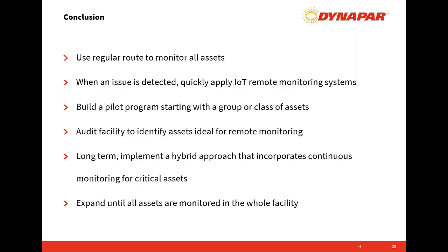And before every read, we have an internal calibration procedure where we check some internal parameters before the data is taken. And the unit is actually self-adjusting from a calibration perspective. So at this point, the unit is good for the life of the sensor and doesn't need any recalibration from year to year.